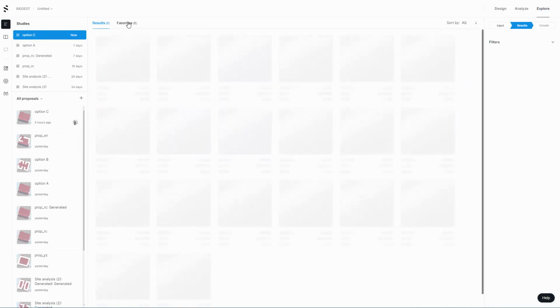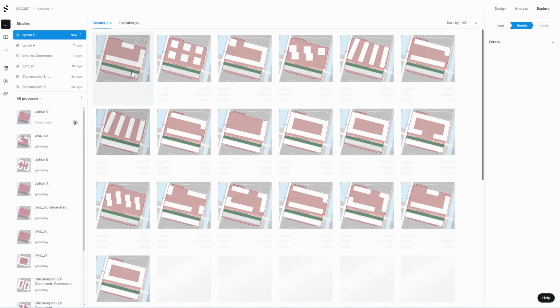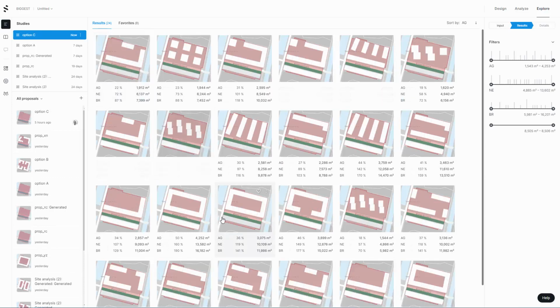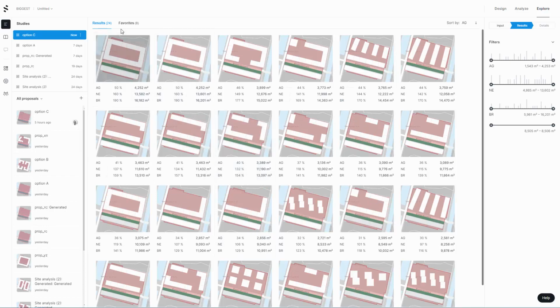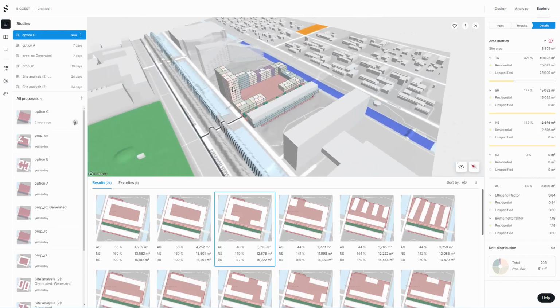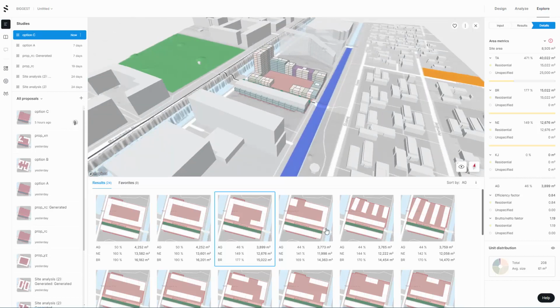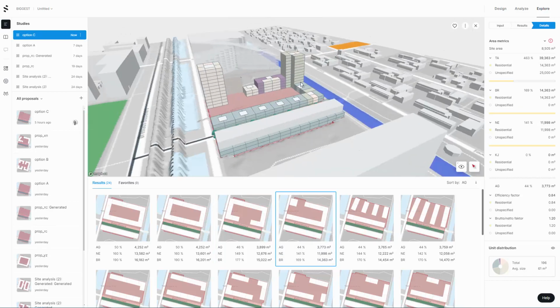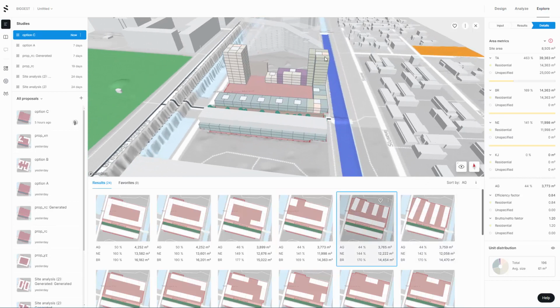So yeah, 12 meters wide, so the corridor might be up to 2 meters if you look at shear walls. We may need to rethink the depth a little bit more, but we're getting a lot more results here. So 24 results have come up pretty quickly. And if we look at these configurations here, we're getting a lot more options. And I have gone with an interesting sort of ratio. So once you click on these here, you'll see some interesting layouts for us, all designed to get at least 3 hours of direct sun.